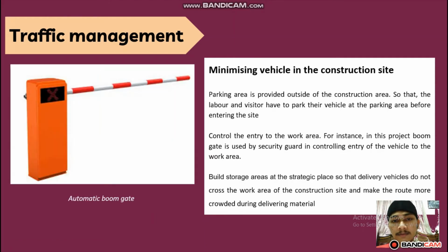Next, the traffic management function is minimizing vehicles in the construction site. For example, in this project, a parking area is provided outside of the construction area so that labor and visitors have to park their vehicles at the parking area before entering the site.